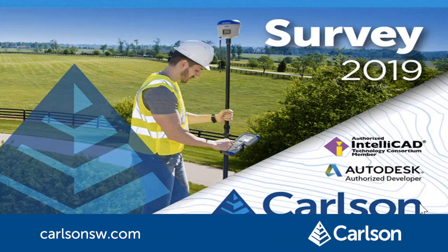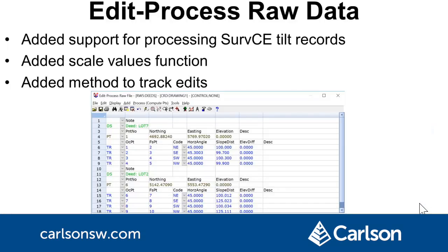Now let's look at Carlson Survey. Edit Process Raw Data adds support for processing raw tilt records from CIRCE. There's a new scale function that can be used to convert values between metric and imperial, and there's a new option to track any edits in the spreadsheet that keeps a record of the original values.